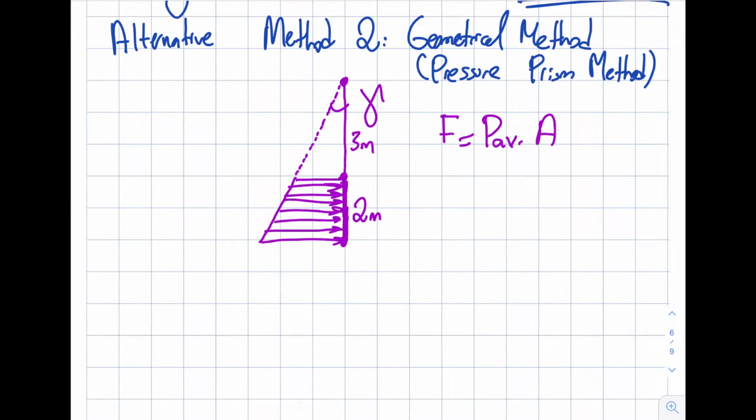That is the question. Well, if there's only one fluid in my case, you can see that this is linear. If I have a linear change, then I can simply calculate PA over here, then PB over here, sum them up and divide by 2. So let's say that I have 2 separate fluids, and fluid one is down all the way to here, and the second one is over here. Well, I'm going to treat them separately. I will do F1 from here to here, F2 from here to here, and it will still be linear within each fluid. This is going to be point A, this is going to be point B.